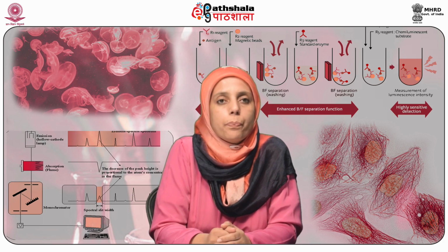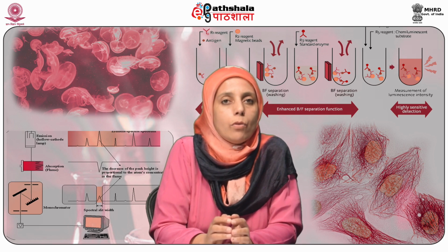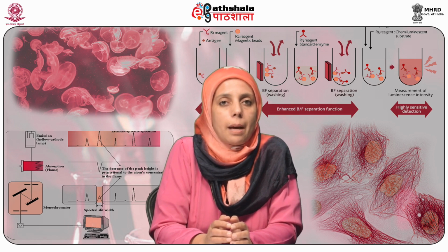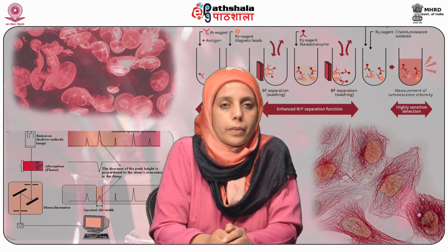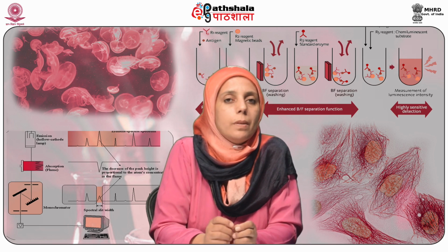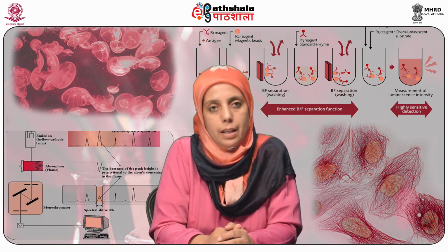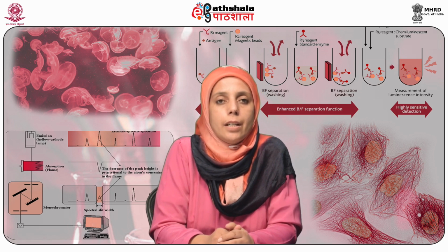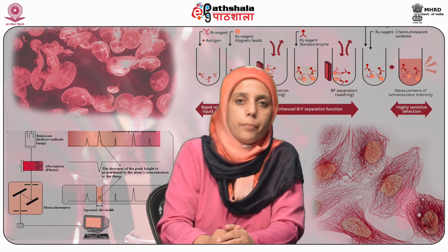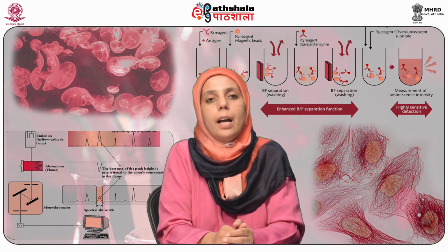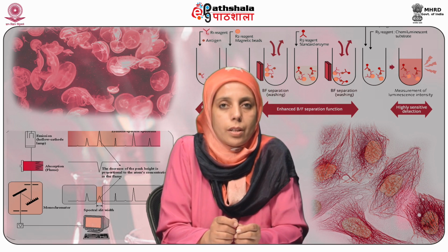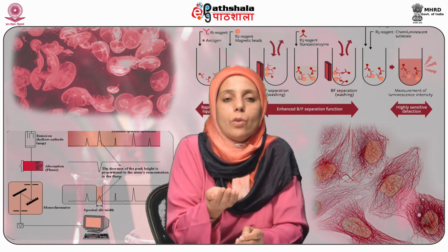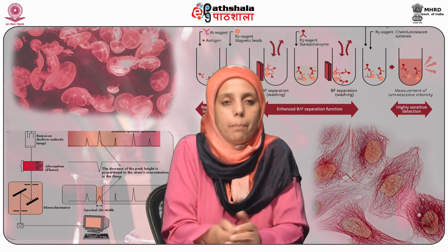So what we need to do is weigh an amount of soil sample and place it in a 100 ml beaker. The sample quantity should be less than 2.5 grams per analysis. Water is added to the sample and concentrated nitric acid is added. It is then mixed with a glass rod and covered with a non-ribbed watch glass with concave side up. Concave means you have a depth on the upper side.